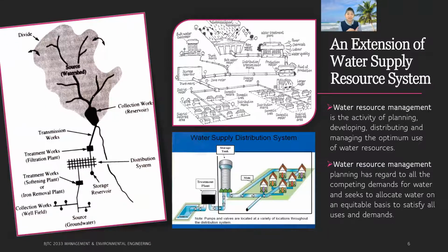So when we do the design, my background is engineer, so I will do the design. So usually when I design this, how do I know how much water I need in this area? During the design system, for one single-story house, we assume there are 5 persons inside: father, mother, two children, and one elder. Okay, we assume at least there are 5 persons inside.